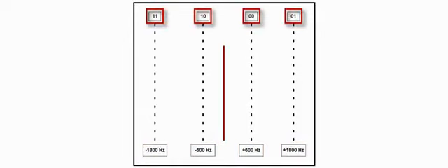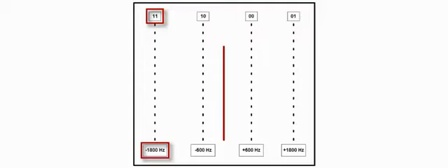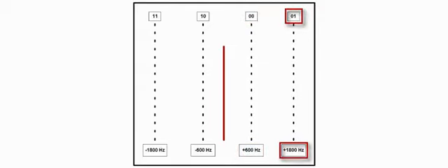Each offset frequency represents a symbol. Each symbol consists of 2 bits of data. A minus 1800 Hz frequency offset represents the symbol 11. A minus 600 Hz offset represents the symbol 10. A plus 600 Hz offset represents the symbol 00. And a plus 1800 Hz offset represents the symbol 01. The carrier is illustrated as being at the center frequency, which does not represent a symbol.